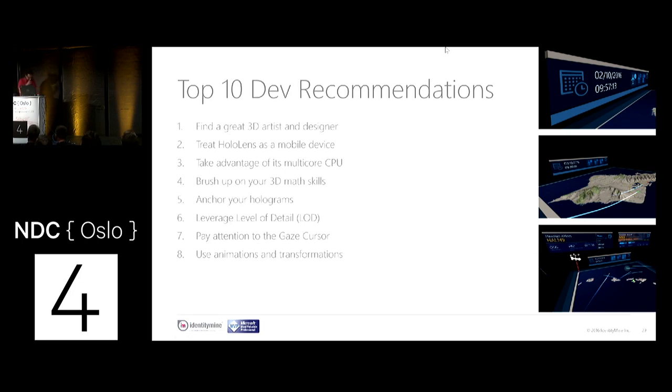Yeah, use animations and transformations to let your virtual objects behave like real world objects. And yeah, this is also a nice one. If you have a bunch of Unity projects, you probably also have a few reusable scripts. And the naive approach would be to copy those script files between all the different projects. But this is not nice, because when you have a bug or want to change something, you have to copy all the stuff.